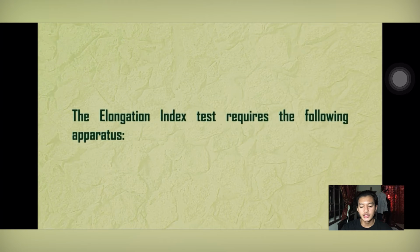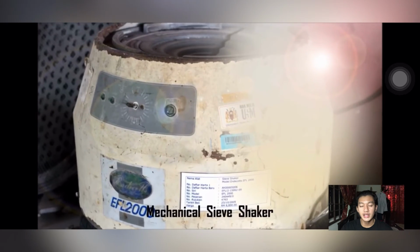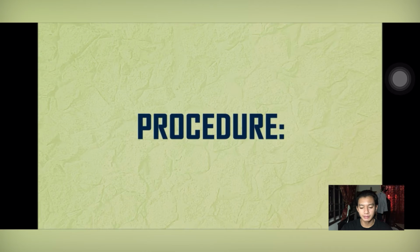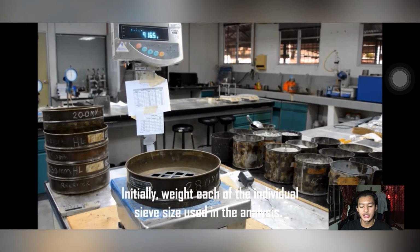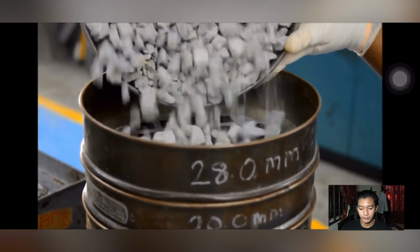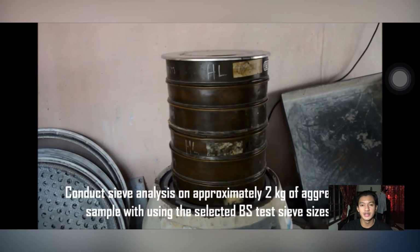The elongation index test requires the following apparatus: length gauge, BS test sieve, mechanical sieve shaker, tray, and balance. The procedure. Initially, weigh each of the individual sieve size using the analysis. Secure a representative sample of aggregate. Conduct sieve analysis on approximately 2 kg of aggregate sample with using the selected BS test sieve size.